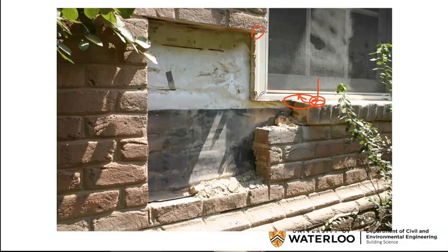Now, what do you mean, Marley, by doesn't go past brick? Oh, I just meant that the flashing doesn't extend past the brick either. Yeah, well, I think that's actually a pretty big deal. So here's the flashing, and it stops about 1.5 inches from the outside. So it delivers water, but it doesn't deliver it all the way to the outside. And you can see from this picture here that it's just filled with mortar, right? So the water's not going to really go away.